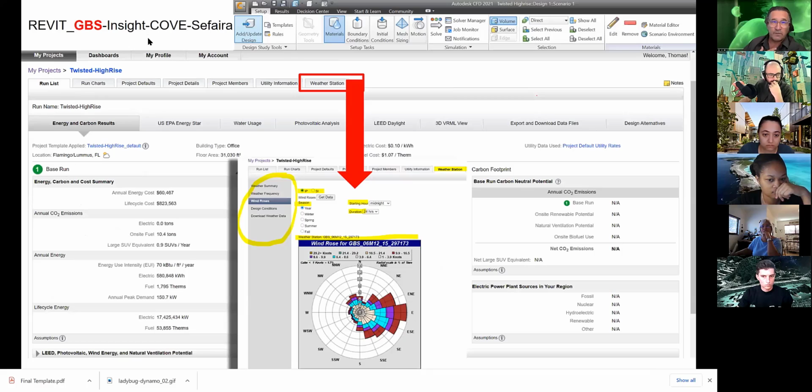How do we start? You have to go to the weather station, and you do the same in Rhino. If you have an EPW file, that's the one you use. Then you look at the wind roses, the season, and the schedules where you need to run the simulation, because you need to define the parameters and the boundaries. If you don't do that, then you work on a CFD for over a year, because you can do all kinds of simulations. So you need to first define the parameters and the boundaries, and with this come the materials, etc.